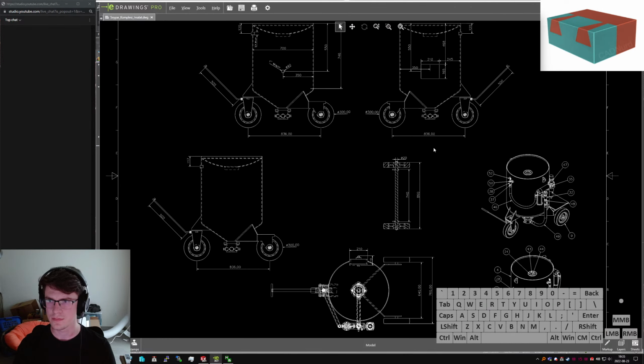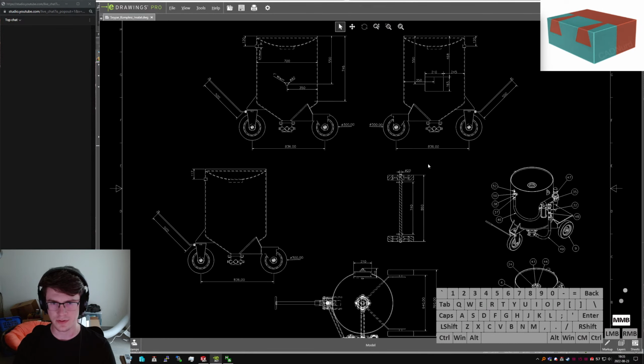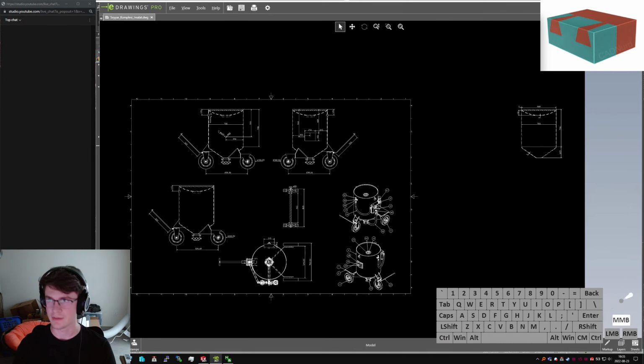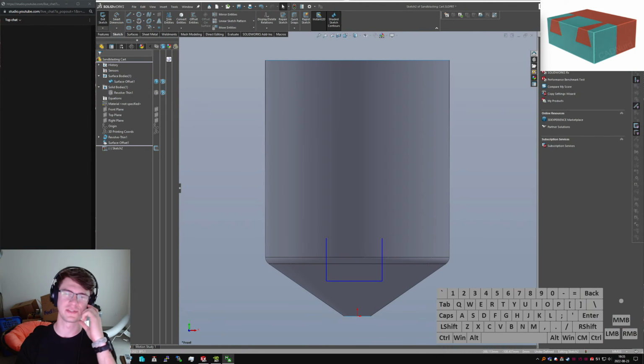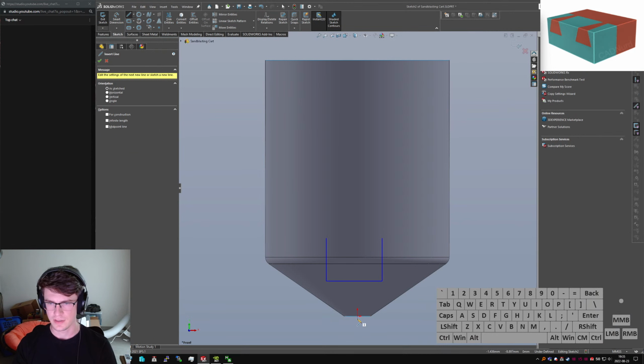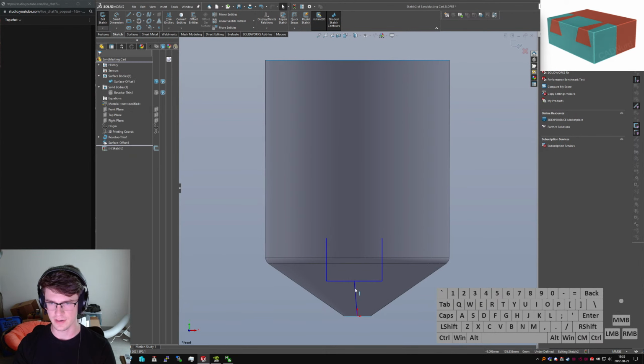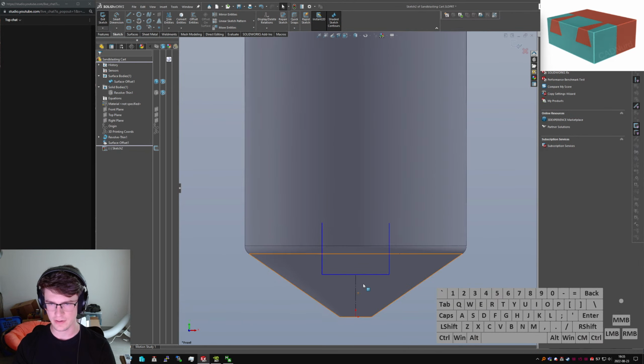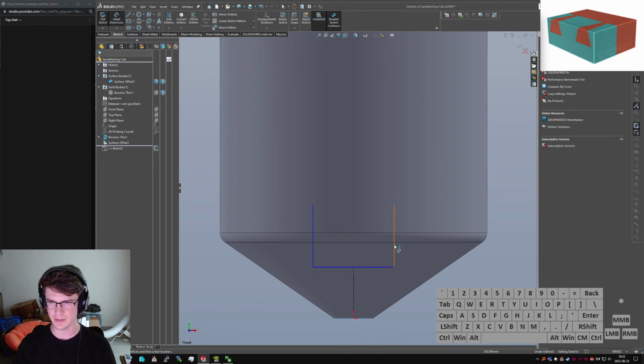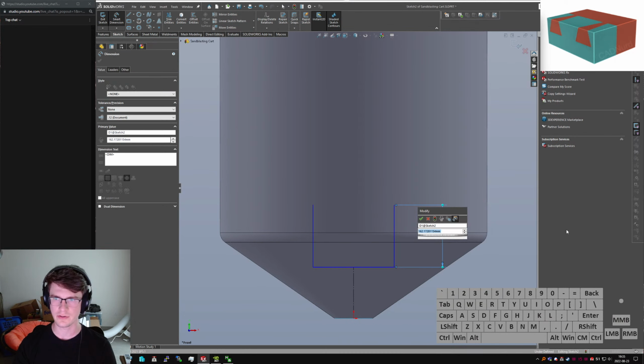Yep, looks like those are all the dimensions I get. Okay, so I'll just wing it from here on out. What's more important is the technique than the exact dimensions. So to align this on a center, I'm going to add a vertical line there, so it's really easy for whoever comes after me to look at that and say, oh yeah, that's probably what he wanted to do here.